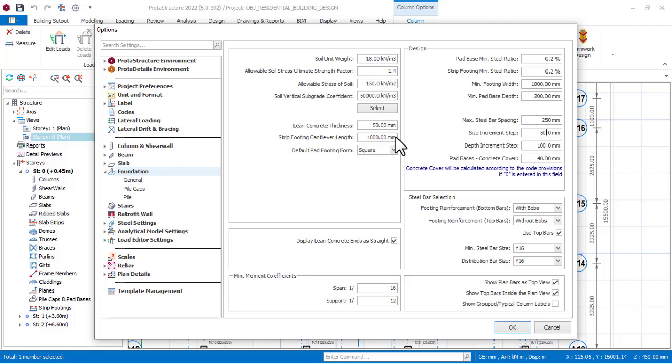Or let me say your footing is 2 meter from your design and that footing is failing and you want to increase the size of the footing, instead of it to increase to 2.1, let it at least try 2.050. You can see that. That's how it is. So I'll use 50 here. You can choose to use 100 here. That's your own choice. But me, I like to use 50, which is, I like to be very economical